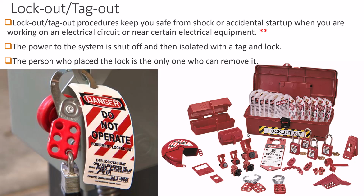And the best way to make sure that it never gets turned back on when you're not looking is to lock out the device so there's no way anybody can do that unless they have the key. So the basic process here is you lock out the equipment after you've de-energized everything and you're sure it's off, and you put a tag on it so people understand it's an official process and not some prank on April Fool's Day or something, so nobody's going to cut that lock, is the idea. This particular hasp that's on there allows you to put 6 locks on there, or you could put another hasp on there and add more locks.